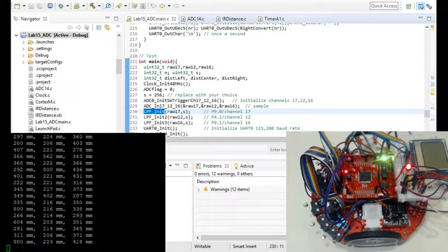And it's introducing the Sharp IR sensors and ADC, reading those in, because they do come in analog and you have to convert that to digital, so you can read it and come out with values. And so you end up with these three different IR sensors that you can use to control this as it navigates through the maze, and that's what the end result is. And then the values you see out there, you can have those set to control your motors and determine whether it's going to go right, left, and if it starts drifting maybe from the center, then you can have it adjust, and also adjust the speed as well, I guess, as it gets down further.